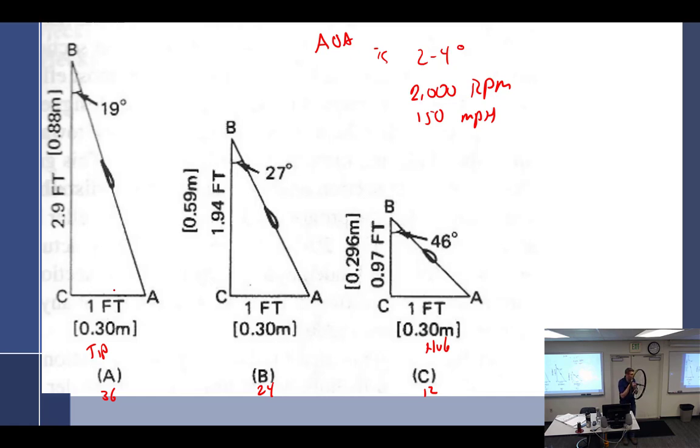The propeller moved forward how far? 1 foot, but it's rotating. So this spoke right here, but you have to think it's much bigger, went this far. If I measure from here to here, that is 0.97 of a foot. But I measured the same thing up here and it had to travel 1.94 feet. Out here it went the same angle, 2.9. It moved 2.9 feet. So you see how that works? We just have to enlarge it to a different scale.